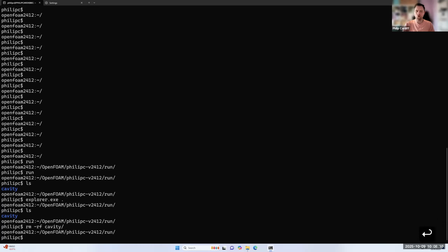Okay, so OpenFOAM comes with a bunch of cases already prepared and made, and they're called tutorials. We're just going to find the cavity tutorial and copy it, and then run it or make changes to it. We already saw that we could type cd $FOAM_TUTORIALS. And you'll see I'm making use of tab a lot. Tab is autocomplete, so it's probably the button you'll press the most on the terminal.